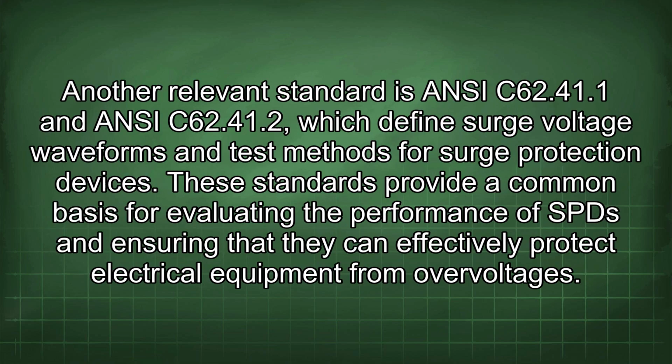Another relevant standard is ANSI C62.41.1 and ANSI C62.41.2, which define surge voltage waveforms and test methods for surge protection devices. These standards provide a common basis for evaluating the performance of SPDs and ensuring that they can effectively protect electrical equipment from overvoltages.